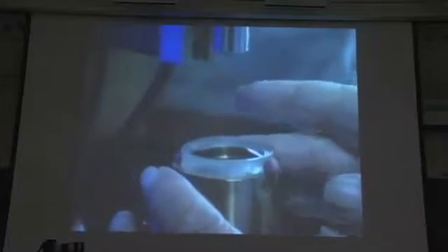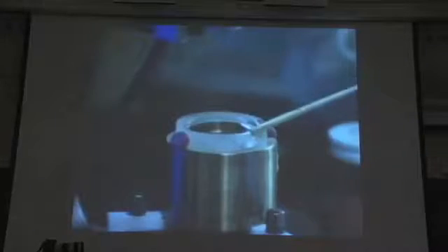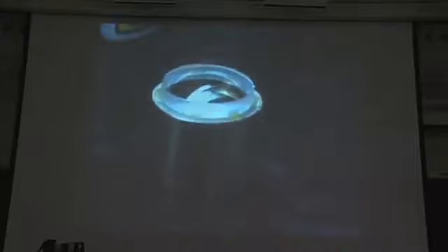Then the convex lens goes to another technician who places it in a holding device. He looks into a microscope and adjusts the position of the lens until it's optically centered. He uses wax to keep the lens from shifting in the holding device. They give the lens another cleaning. Each one must be absolutely spotless before they proceed to the next step. Otherwise, dust particles could become trapped within the optical system and affect image quality.